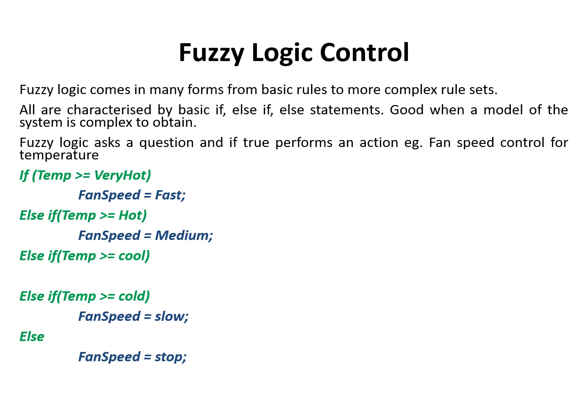So one basic fuzzy logic controller would be if we want to control the temperature of a system, and we have a fan which blows on the system. The more the fan spins, the higher the airflow we have over our component, the faster it cools down. So the higher the temperature, typically the faster the fan should rotate, and the cooler the system, the slower the fan has to rotate in order to cool the object down.